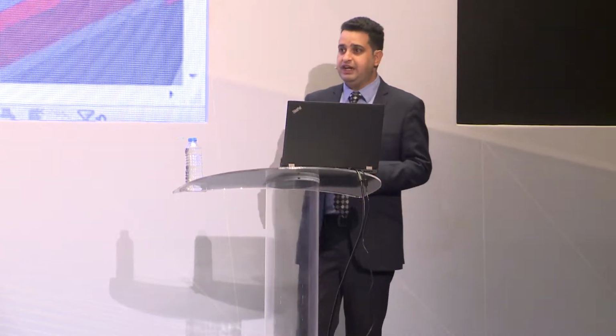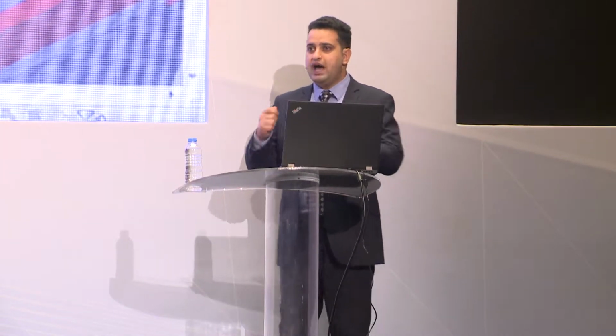Now, after that, once the model has been created, how do you take that BIM information onto the field? So one of the ways is that once you go to the site, you need to have control about where exactly is the hanger I'm going to put in there. So what we're going to do is we'll eliminate the paper and the tape measurements on the site. I have my BIM model, I have my hangers in the model, I need the location of the hangers from the model. I will be taking them directly from the model versus tape measurements.